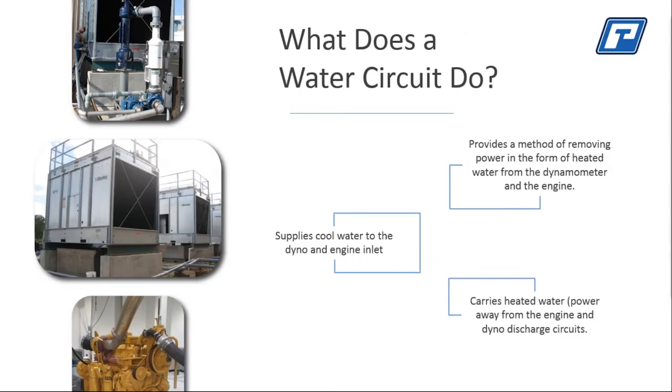All right, I'm going to move on to the next page. What does a water circuit do? Water circuit basically is designed to remove the heat from not only the dyno, the water brake dyno, but also from the engine. You've got to take that into consideration when you are sizing a water circuit.